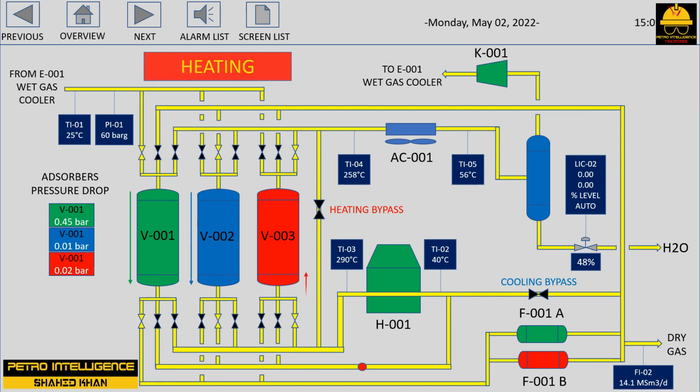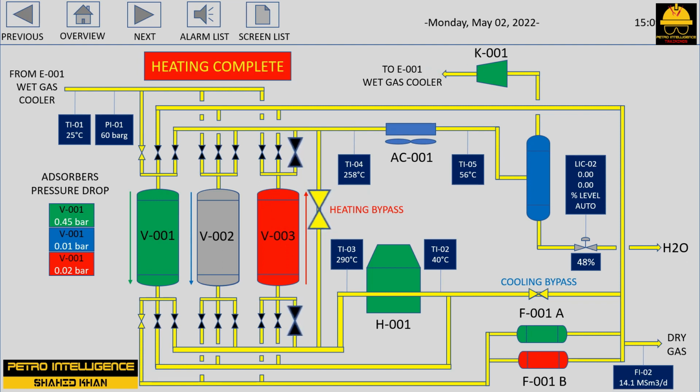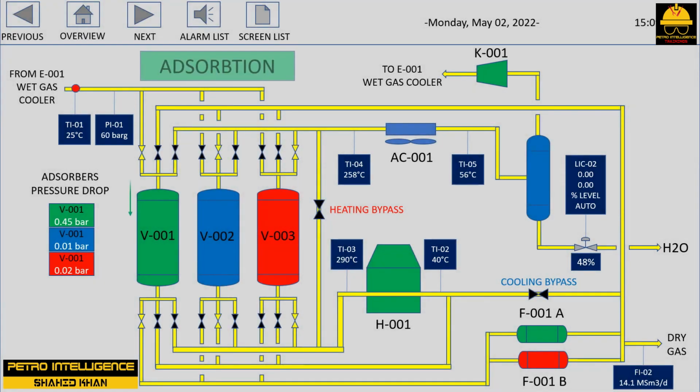In the case of the two-bed system, two different arrangements are possible. The cation and anion resin can be in separate layers or in separate vessels. This would be equivalent to two single beds in series. In the other arrangement, the cation and anion resins are together in a mixed bed. Regeneration of the mixed beds involves more complex steps because the two resins must be separated before regeneration and mixed together again after regeneration. Normally, the resins are separated by size and density differences before the regeneration steps.